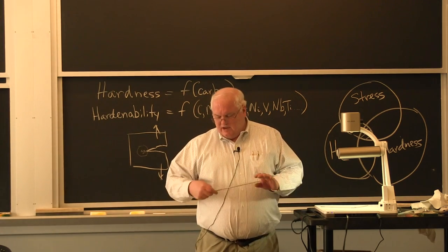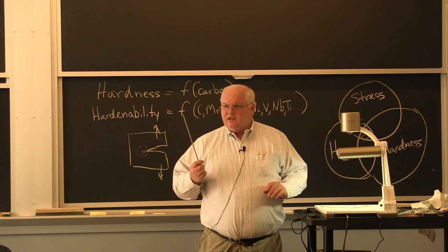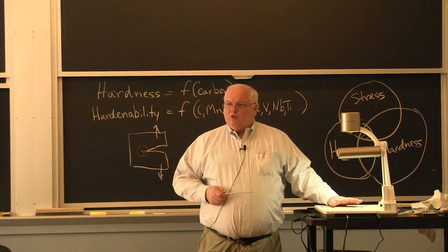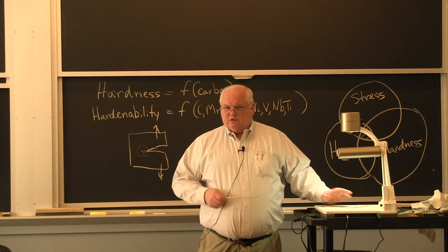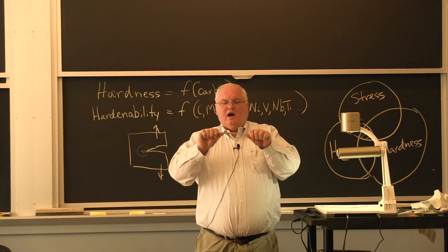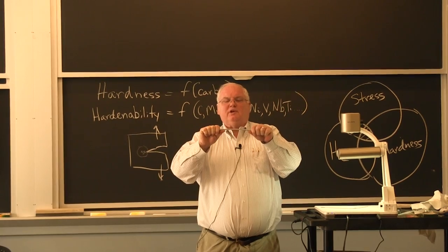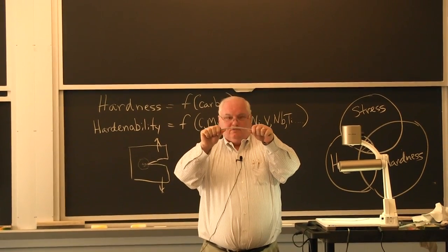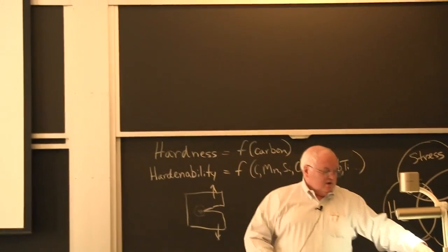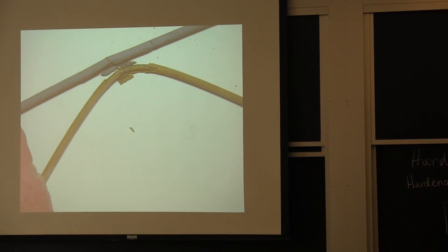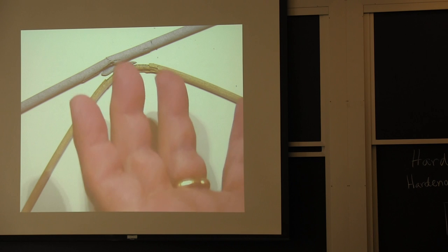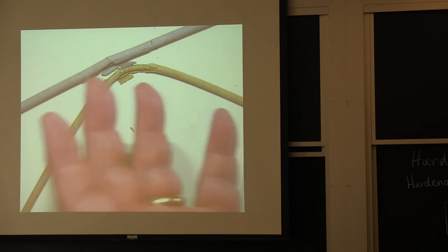If I take a 7018, now unfortunately these 7018s were baked at about 400 degrees Fahrenheit to get rid of most of the moisture. These were baked at a higher temperature, but these have been sitting around in the air. And this one, well, I got about 15 degrees before it started flaking off. Okay? And that's because it's basically a brittle, glassy coating.